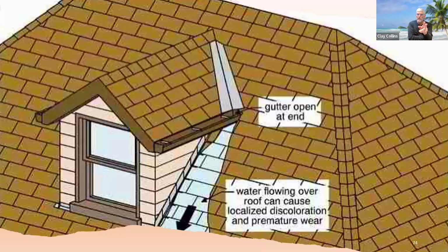And it was because there were almost 4 roofs, 3 valleys coming down to that one section, and it flat overwhelmed it. But even if that gutter hadn't been there with its single downspout, it was going to overwhelm it. So the problem was the design of the roof rather than the downspouts.